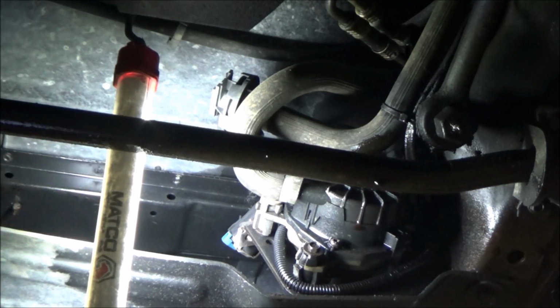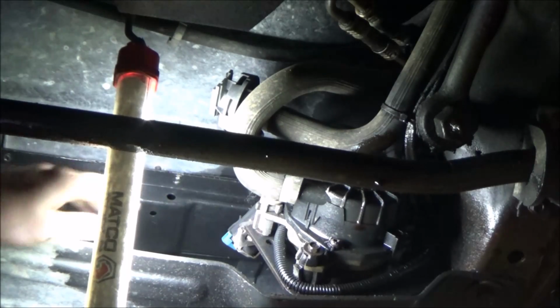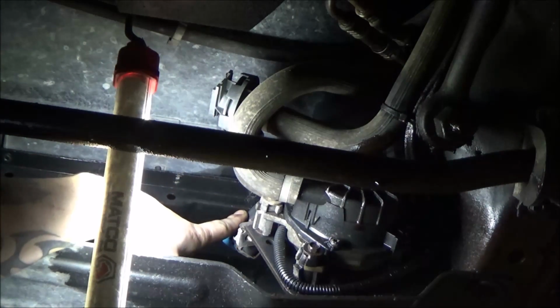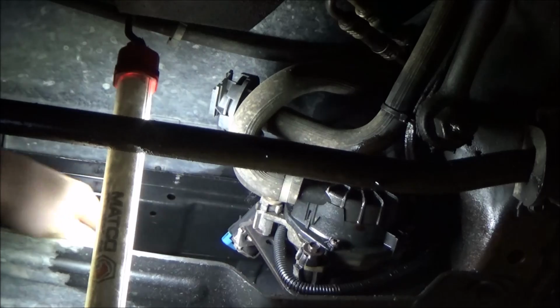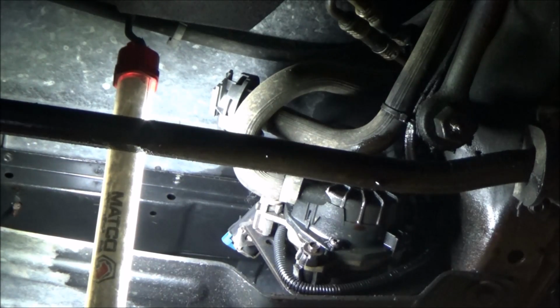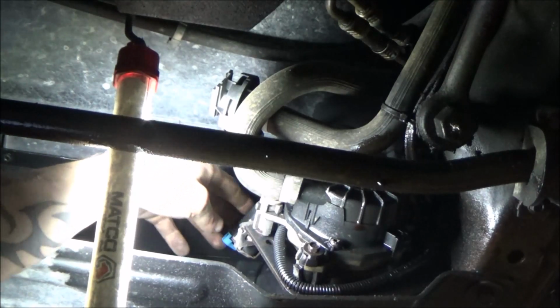So all I'm going to do is use that same functional test we were doing before, where we were turning this relay on and off. And I'm simply going to put my finger on the solenoid and feel and see if I can feel it turning on or not. First, we'll take a listen. So I definitely hear a click up there on the relay. But I am not hearing the solenoid clicking here, guys.